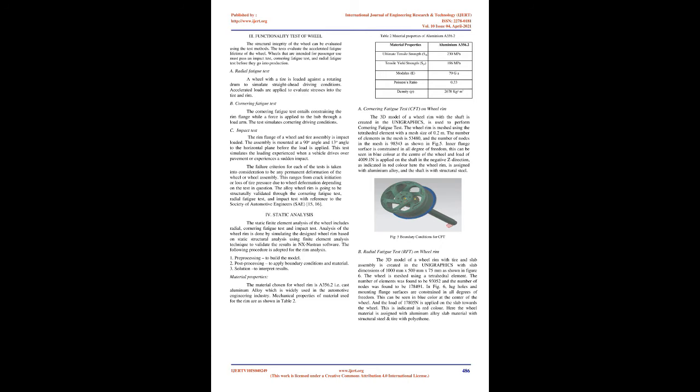By taking rim diameter and rim width, the offset, center bore and bolt pattern can be chosen based on manufacturing feasibility in CATIA V5. Using the CATIA V5 commands, modeling of the wheel rim in 2-dimensional and 3-dimensional planes is done. Selecting the XY plane, the rim profile is sketched in 2D with respect to the dimensions with the center axis at the origin, and considering the center axis, the sketch is revolved around 360 degrees.